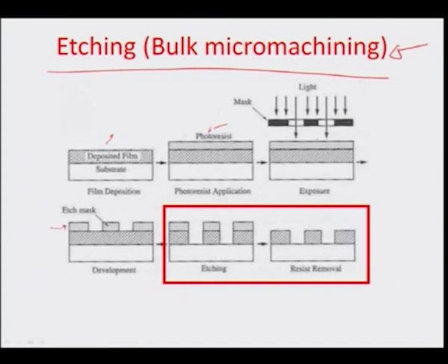So, the resist is patterned here on the surface, thus exposing these regions of the deposited film, and then you can actually etch selectively because the photoresist may not be etched; it is a sacrificial mask on the top. So, you etch selectively, thus etching these portions where the resist was no longer there or did not protect, and so you can have these blocks of the deposited film on the top of the surface as you remove this resist using some other methodology. So, you can use a variety of these processes together to formulate micro features and micro patterns.